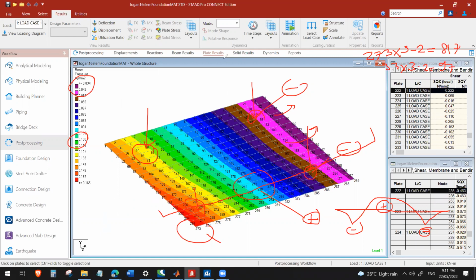Now remember that in the earlier derivation of stiffness, we idealize a spring per node, right? And we found this is 78,250 Newton per meter stiffness per plate. Okay, and the tributary area is this, right?